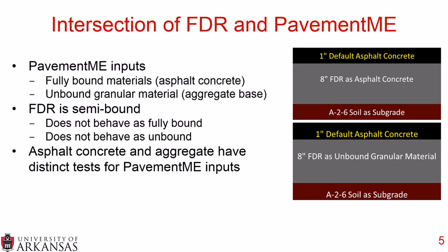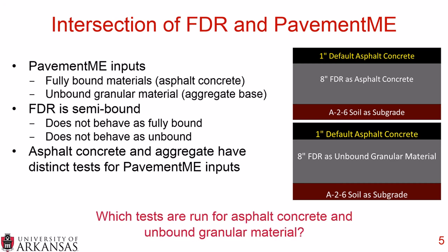So PavementME has distinct tests that need to be run for fully bound materials or fully unbound granular materials as inputs. And so what Sadie did is she took a look at the exact same material, full depth reclamation, but she ran tests for asphalt concrete on the FDR materials, and she took that same material and she ran tests for unbound granular material.